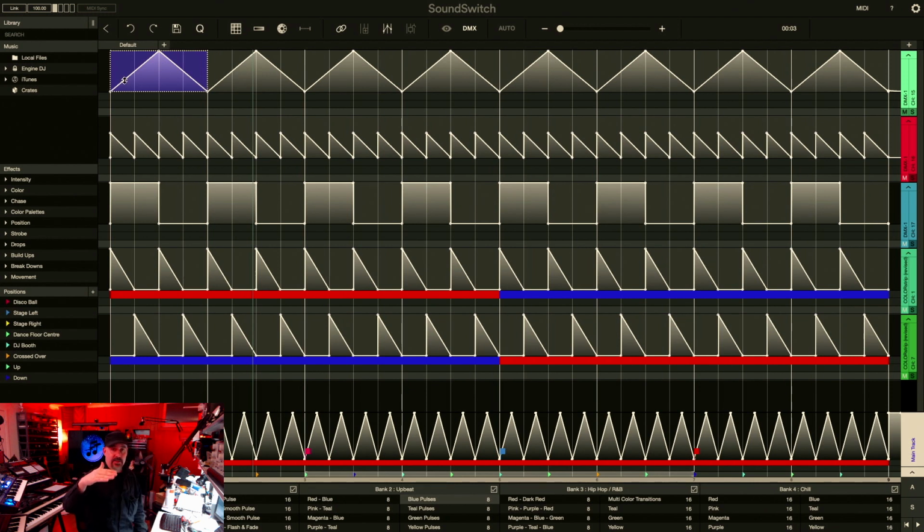So what is actually happening? The DMX is sending out 0 to 255 and then back to 0. Our project is converting that to MIDI numbers 0 to 127 and then back to 0. And I have that mapped in OBS to screen rotation. So 0 would be no rotation, and then it's going to gradually spin around until it does a 360. So max value will be 360 degrees, and then it's going to start going back the other way and rotate back to normal.